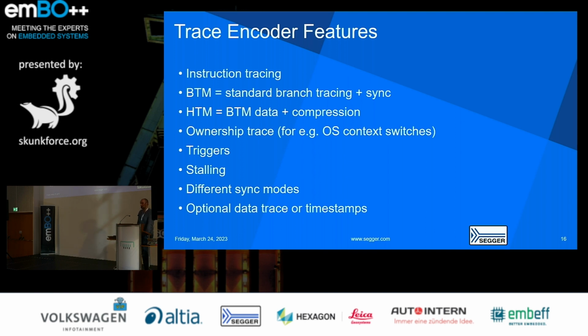You have stalling. Stalling is a feature where, if your interface is risking overflow, where you would lose trace data, you can enable this. And every time the overflow is risked, it will temporarily halt your CPU until the pipeline is cleared and then continue. This, of course, makes this intrusive again. So this is something to keep in mind. But it's a nice trade-off. If you really don't have the pins, then this is the way out if you still want to have some kind of system insight via hardware tracing.